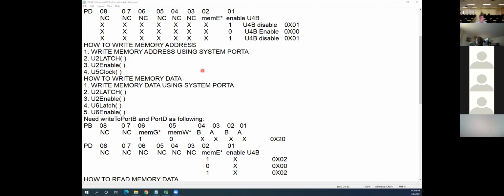So you're saying just use P clock. When you call the function U5 clock, I can understand right away you want the clock applied to U5. So you would create a definition for U5 clock that was just P clock. Your function definition would be void U5 clock, and then inside the braces you would put P clock. Yes, sir. Okay, thank you.